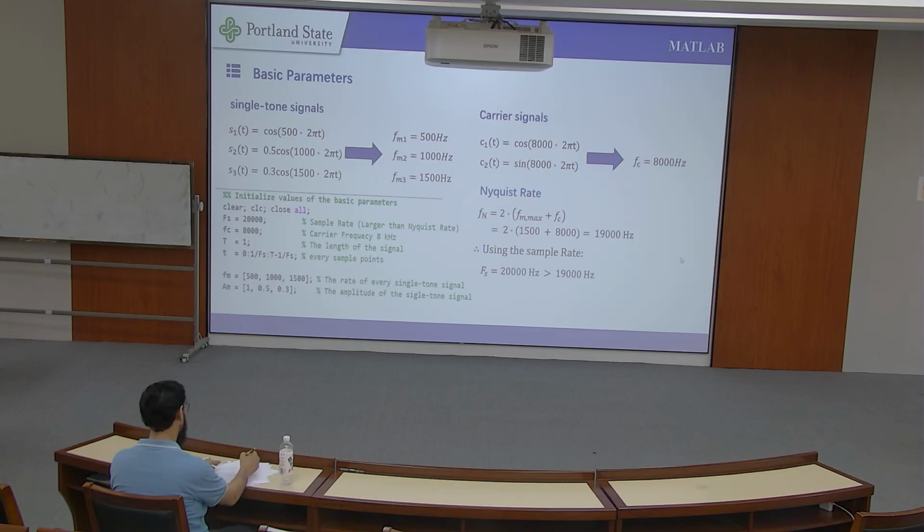In this part, our goal is to generate an SSB signal and verify that it works by looking at its frequency spectrum. So why do we want SSB? Because traditional AM modulation transmits 2 identical symmetrical sidebands, one on the left and one on the right. This actually wastes half of the bandwidth. By using the phase shift method, we can chop off one unwanted sideband and keep only the other half. This saves half of the frequency space and makes our transmission much more efficient.